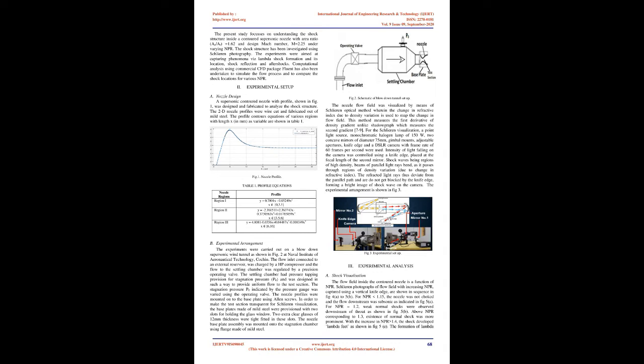Computational analysis using the commercial CFD package Fluent has also been undertaken to simulate the flow process and to compare the shock locations for various NPR. 2. Experimental setup. A. Nozzle design. A supersonic contoured nozzle with the profile shown in Figure 1 was designed and fabricated to analyze the shock structure.